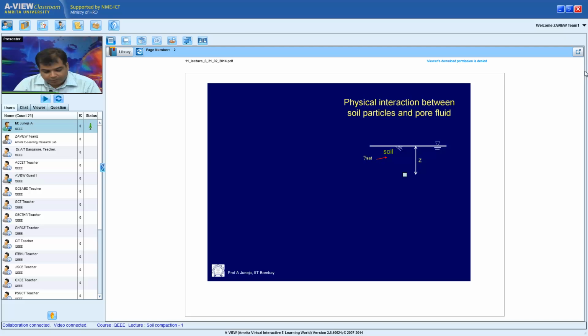I'd like you to look at the small sketch, the cartoon drawn on the right hand side. The sketch shows the ground level. Usually ground level is shown by a hatch, drawn below the straight line. It shows the ground surface. And if an inverted triangle is drawn, it shows the groundwater table. We'll look at this groundwater table in a while, but what it represents is that the surface of the water is at this level.